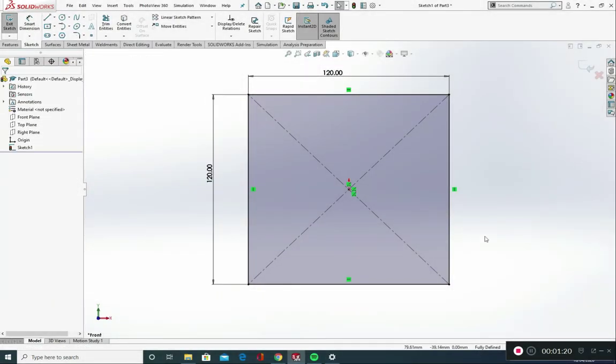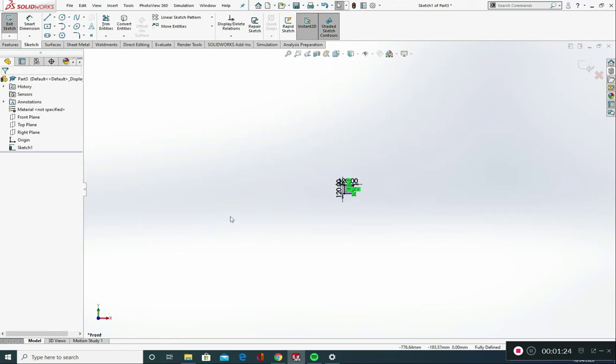Okay, here is hack number 2. Hack number 2, we've all done it. We've all been there. We've been on SolidWorks and all of a sudden, okay, we are in space and we have lost our model, lost what we're drawing. Really great way of finding this. Press the letter F on your keyboard. You'll get a centralized view of where your model's gone.